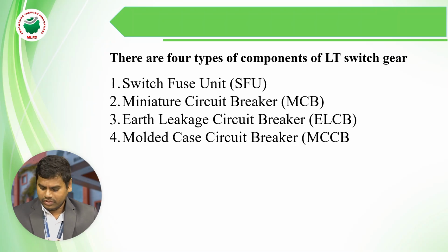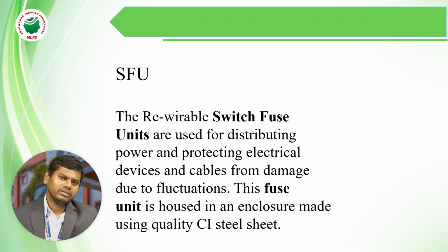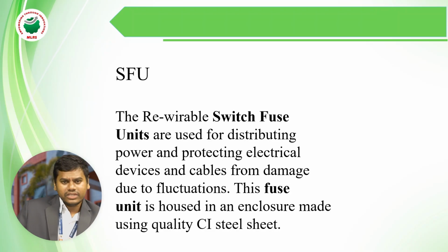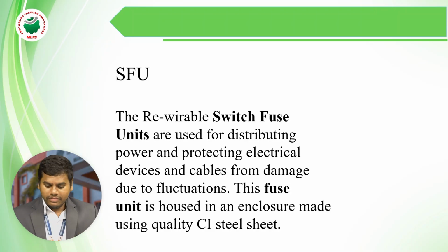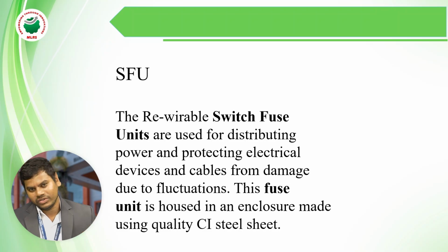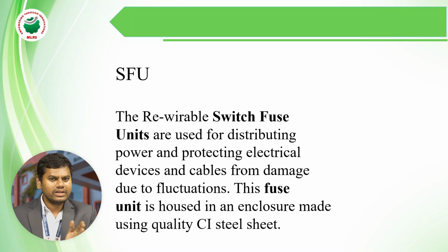Now I'm taking the first one, SFU, switch fuse unit. This is a rewirable switch fuse unit, and it is used for distributing the power and protecting electrical devices and cables from damage due to fluctuations.